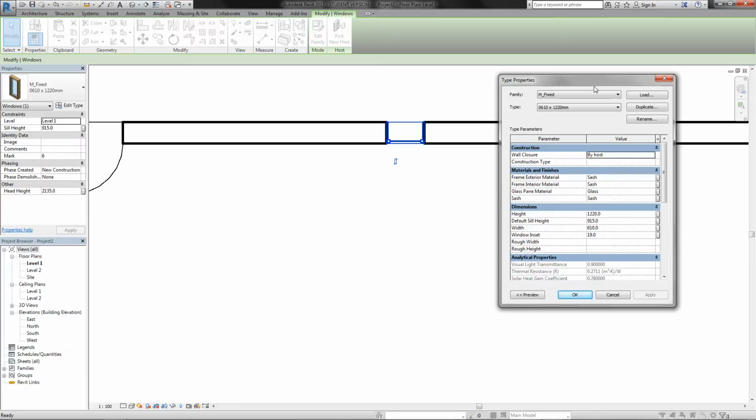Okay. So let's say we have different types of doors. Like, let's say we have a door like this classic door which is glass, and that door which is wood and solid. So that's a family of door, and that's a family of door. Within that family, we have different types. Like this door could be a meter wide, or 2 meter wide, or 3 meter wide. So there are different types of glass doors for that family. And for that door, same thing. 1, 2, and 3 different meters. 3 meter wide are different types of that family of wooden door.